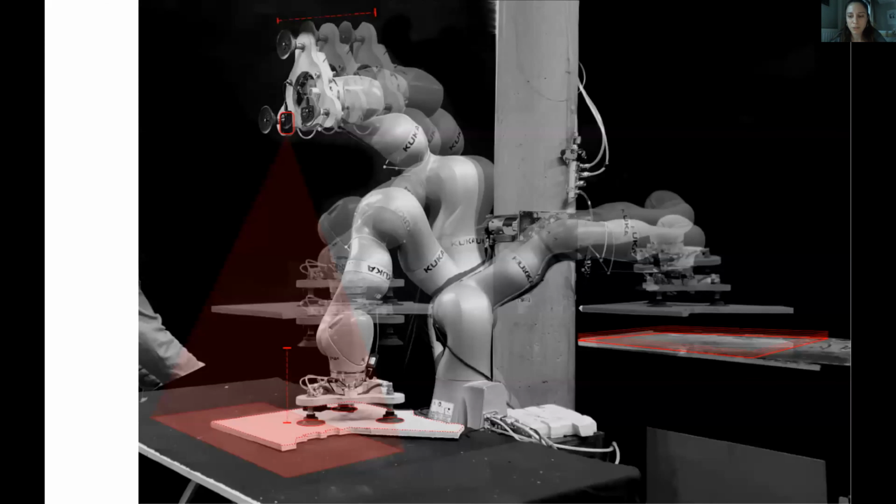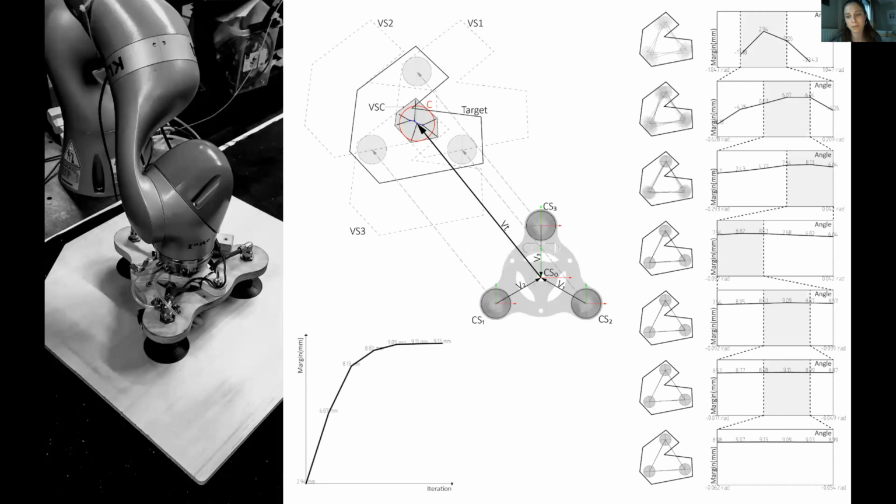The problem with the robotic fabrication process is that we have to manually locate and calibrate the pieces and give this data to the robot, which is time consuming and also not practical with a big amount of pieces. With the autonomous scanning system, the robot can calculate the size, shape, and thickness by itself. And we also create the gripping strategy, which means that the robot can find the pieces without calibrating each piece manually one by one, and can also calculate the center of the pieces to pick them up.